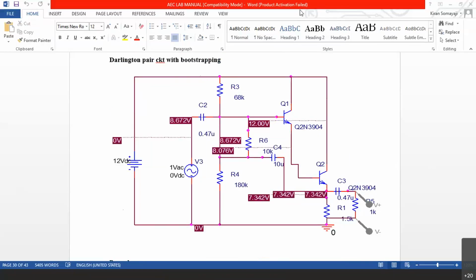Okay, the answer is, if this 1K load resistance is already there, then when you connect that, the output impedance is always much lesser, it is in a few ohms. Now this 1K comes in parallel, and the 1K is inclusive of the output impedance there, isn't it?